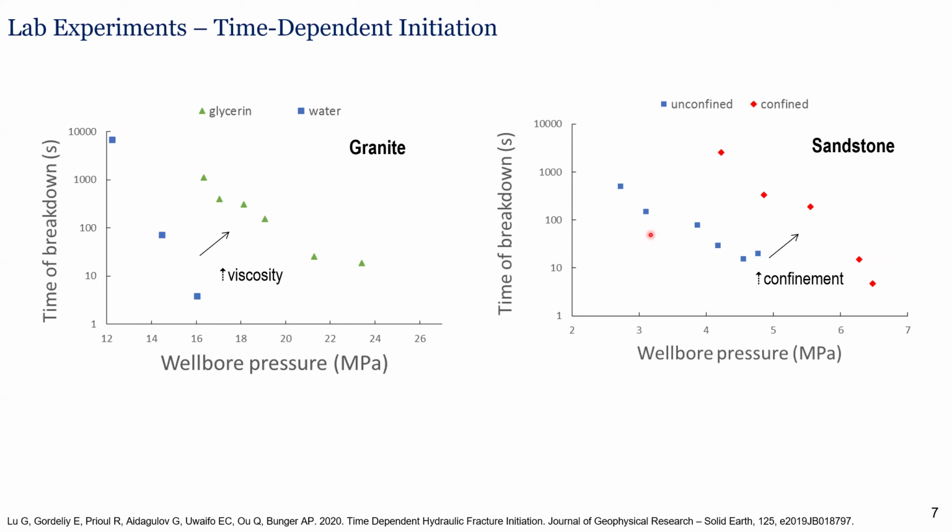The problem here, especially if you look at these sandstone tests, is that the time scale for diffusion into the near wellbore region is way smaller than these hundreds and thousands of seconds that we see to breakdown. And even in granite, these are completely drained tests. The nature of diffusion is that you get a non-time dependent undrained solution when you do everything fast, and you get a non-time dependent drained solution. And the transient part that connects those is fairly narrow in terms of the time scales that it impacts.